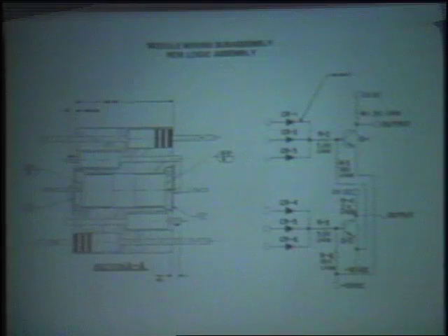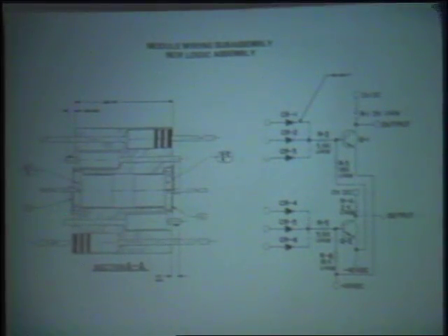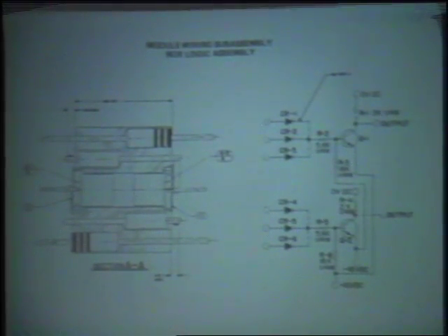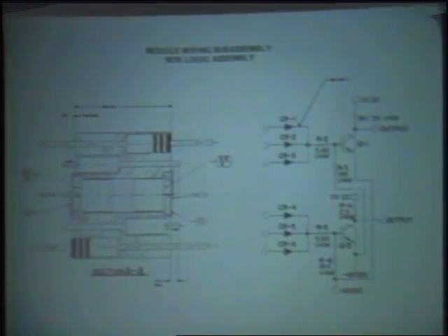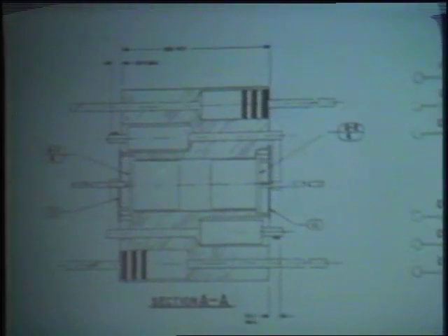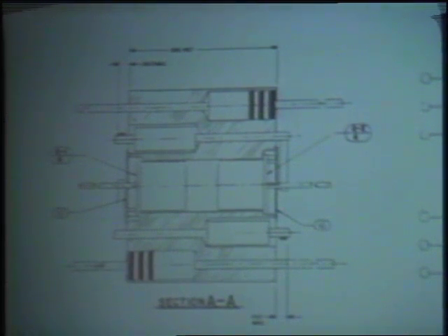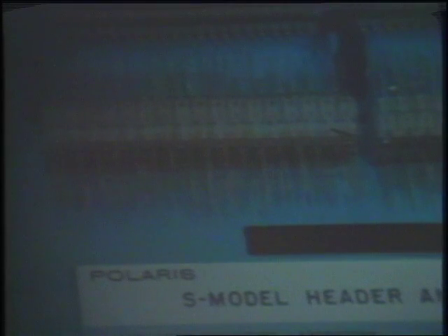The logic schematic is shown here on the right, and the subassembly in welded cordwood construction is shown on the left. These are the transistors, two of them here for these two transistors. Then the various resistors and diodes are with welded interconnections. These little modules were glued together, shown across here, and prepared to mount in a header. The next slide shows this completed module prior to potting. A welded matrix which interconnects the logic and actually makes the function of the logic is shown here. It's on each side of the module.